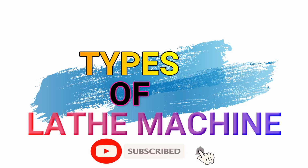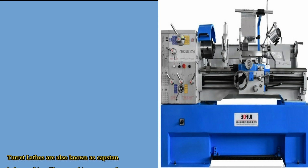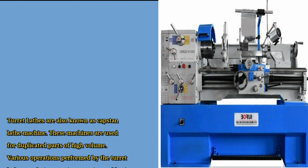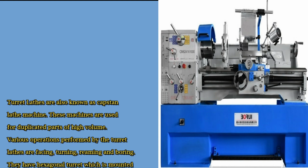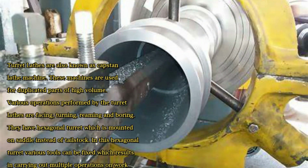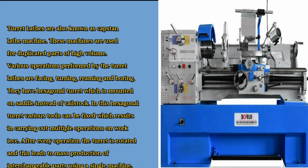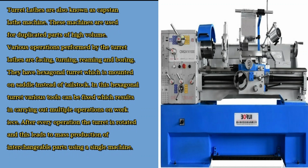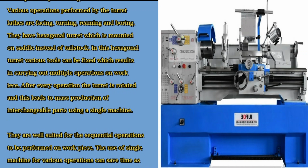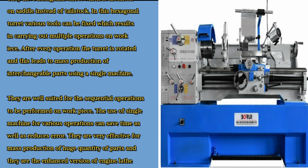Types of lathe machine. 1. Turret lathe machine. Turret lathes are also known as capstan lathe machine. These machines are used for duplicated parts of high volume. Various operations performed by the turret lathes are facing, turning, reaming and boring. They have a hexagonal turret which is mounted on the saddle instead of a tailstock. In this hexagonal turret various tools can be fixed, which results in carrying out multiple operations on the work piece. After every operation the turret is rotated and this leads to mass production of interchangeable parts using a single machine.